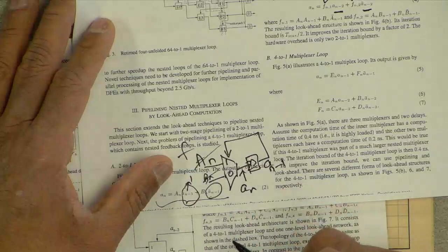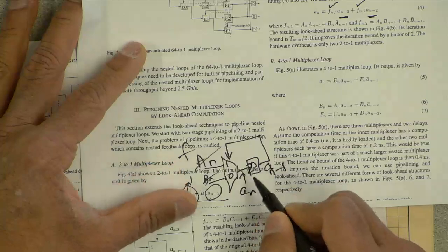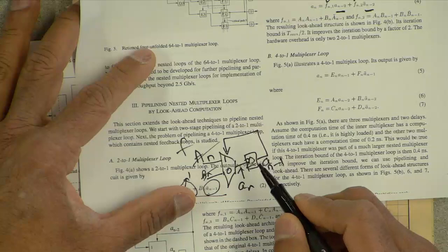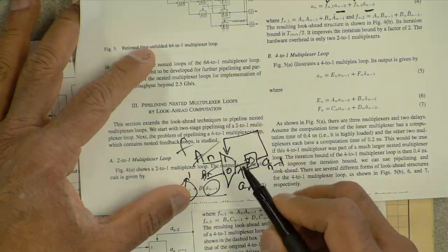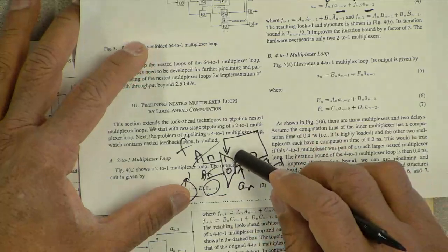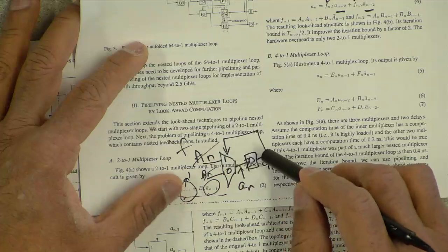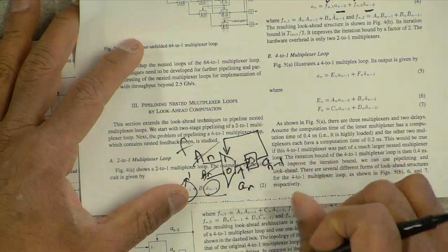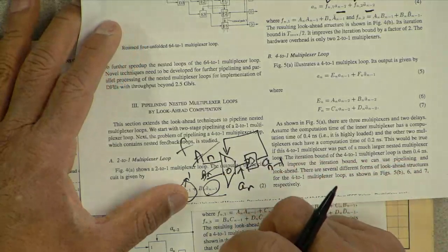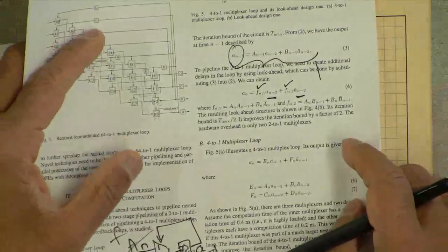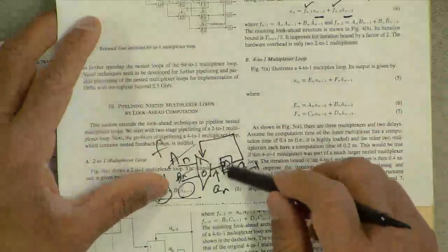Okay, so having those 2 delays is important to us because, for those of you who took the other class, the unfolding algorithm can be applied to parallelize this so that in the parallel filter each of these will become 1 delay. I'm not going to talk more about that because it's hard to follow unless you take next semester's class, but it can be done. So we can parallelize, but before we parallelize we need more delays in that loop.